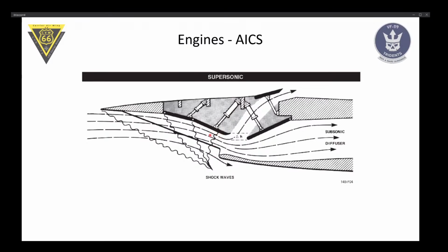Now, as we change our speed from, let's say, Mach 1.5 to 2.2 or 0.7 or even 2.0, these shock angles would change unless we adjust these ramps, because we want our four shocks to focus outside of our duct. Because if they were to cross each other within the duct, we would have a lot of bad aerodynamical effects happening here.